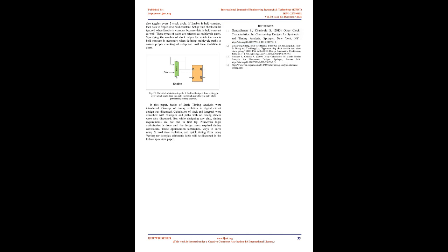Clock-to-Q delay is the delay between the active edge of the clock and the change in output of the flop. Considering all the delays, the setup and hold time constraints are expressed in equation 7 and equation 8 below respectively. All flops in the design should adhere to these equations, else the flop enters a metastable condition.